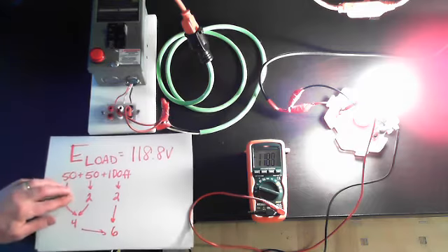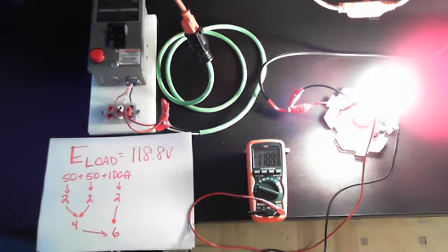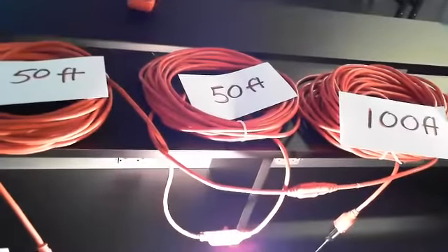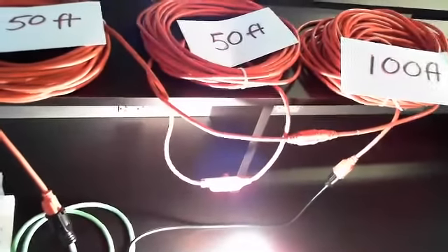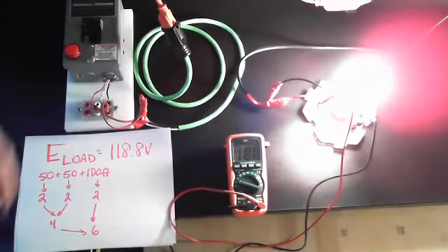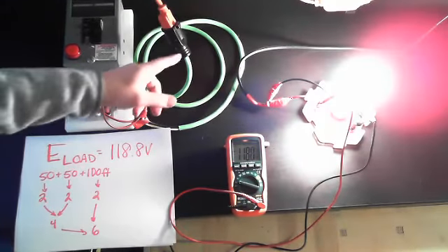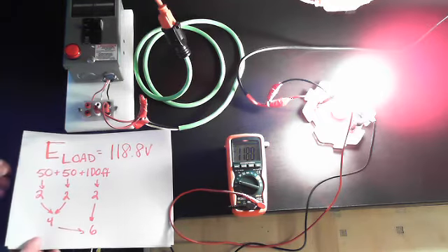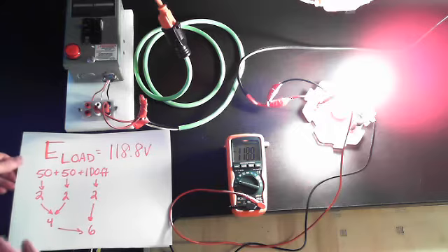6, everything. So now we can kind of reflect back on how we added the circuit elements, how we added the connections of the extension cords. And we have our total 3 extension cords here, all wired in series. So we have 200 feet length. And of course, we have 6 connections, not counting the initial connection here. So really, we have 8 connections. But for extension cord, we have an additional 6.